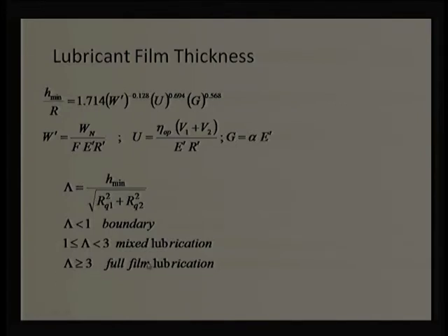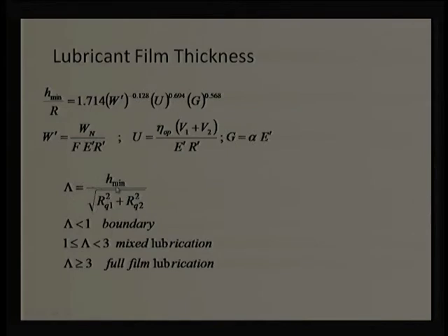Generally, on the rolling surface, near the pitch circle diameter, this kind of surface is possible when there is high pressure that is deforming the surface, and there is a lesser surface roughness. So, this regime depends on both. First is the H min, the minimum film thickness, a minimum separation, and it depends on the surface roughness profile. And what we have seen in previous slides, if the manufacturing process is not very good, we are going to get high surface roughness, and surface roughness may be 3 microns or 2.3 microns even after running-in time.